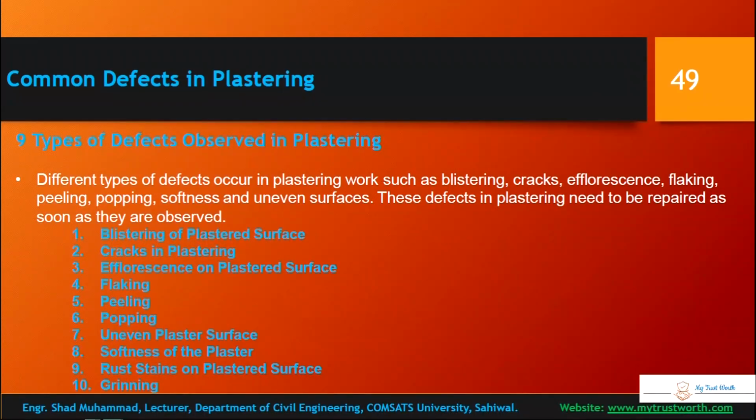If your project has been in phase 5 or phase 6, monitoring and control, and you have handed over your project to the client, then some provisions are provided in contracts that within 1 year, if some defects are visible in the structure, it's up to the contractor to fix and repair those defects.